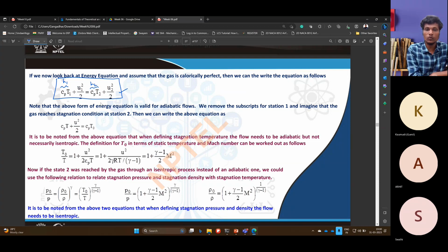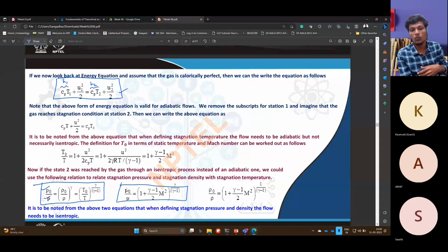Not only the momentum equation, momentum conservation, but also mass conservation you can apply all the time, while analyzing the problem correctly. We are just simplifying instead of using many terms, by stating stagnation pressure kind of conditions and static pressure kind of conditions. We want to directly obtain the corresponding properties without always going to the conservation laws. That's why we always end up with simple algebraic relations that involve only the Mach number, or only the stagnation pressure or the static pressure.